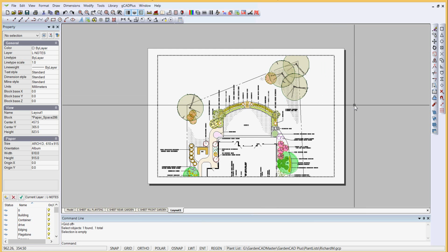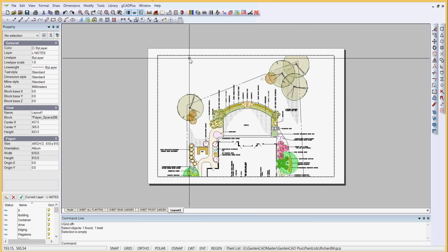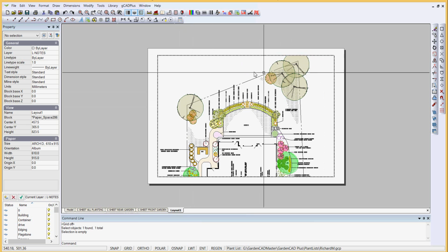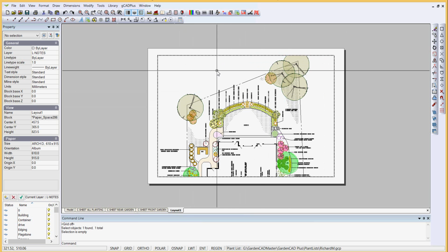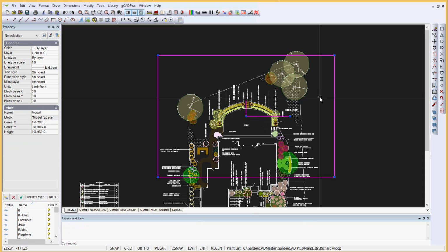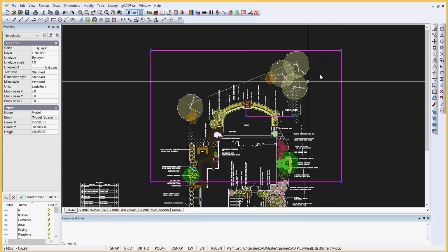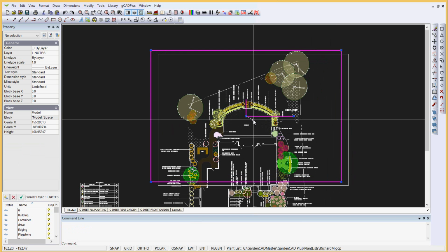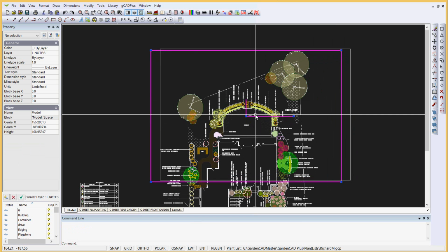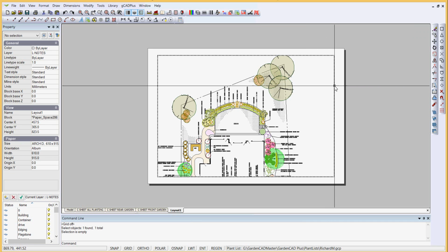There's a slight trick to this stage in that the floating viewport is indicated with a dotted mark. To get rid of that dotted line type, just double click anywhere in the design and that will disappear. So to reiterate, to set it, double click there. We could increase the size a little. We could just position things a little differently. You can see I'm just moving things around, then right click and display on the layout.